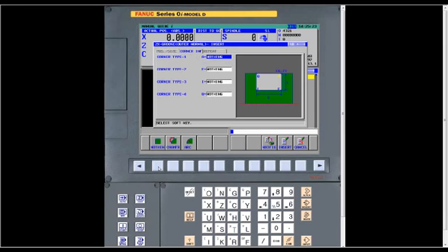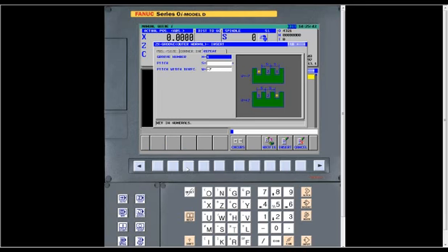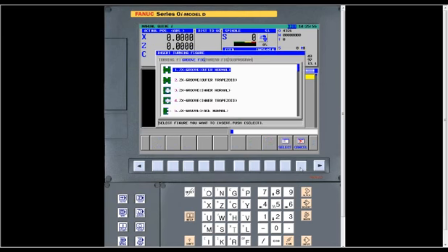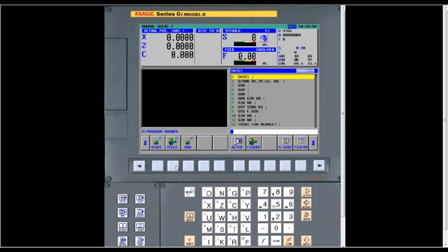Another good thing about the grooving, you've got the capability of, on all 4 corners, bottoms also, where you can either define a chamfer or an arc, or nothing. You can make it a sharp corner. And then obviously you can do multiple grooves. However many you want, the pitch, and then which direction they go, whether Z minus or Z plus, based on the geometry of your print. So that's the grooving cycles.